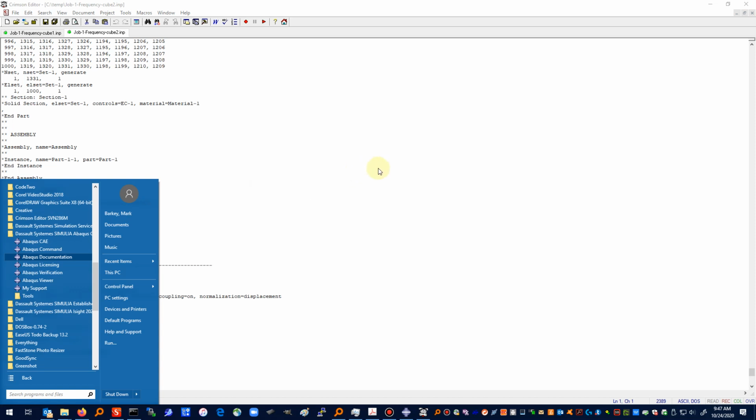Alright, so this is a really important thing to do, is you should really understand what all these different parameters are doing to your finite element program. Yeah, I know I said this kind of fixed our issue here. But we look at this, and it says using values larger than the default values for Hourglass control can produce excessively stiff response and sometimes even lead to instability if the values are too large.